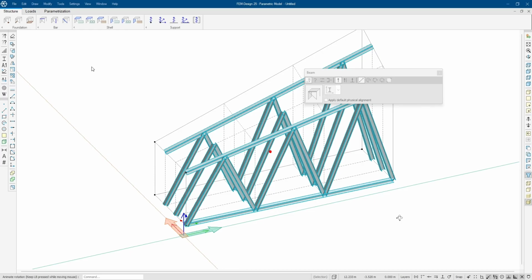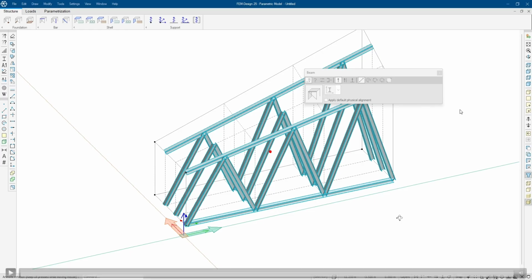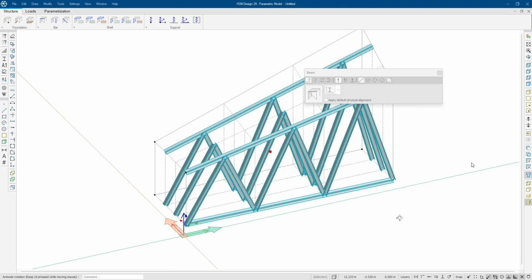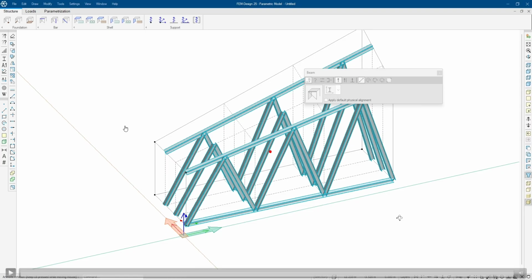There's a question: can we parametrize the piles? Like we can increase the number of piles. Yeah, you can make a grid out of those piles. So if you want to do the pile cap example, you can put the number of piles as a parameter. Yeah, you can have spacing x and spacing y, and then it automatically places those on the edges or also in the mid parts, however you want. Yeah, it's a grid that you can use to do that.